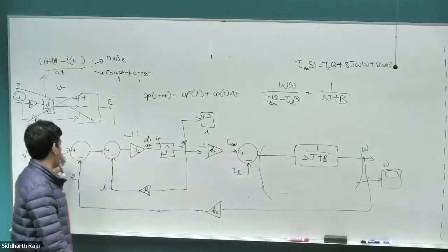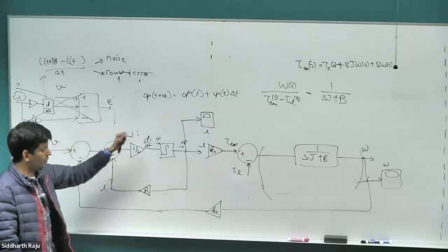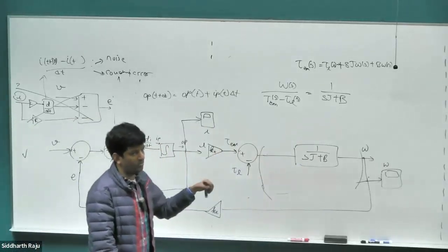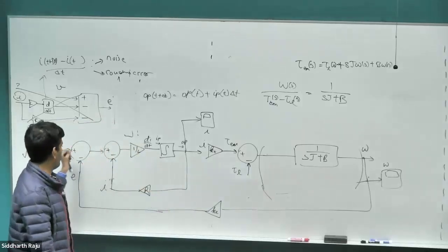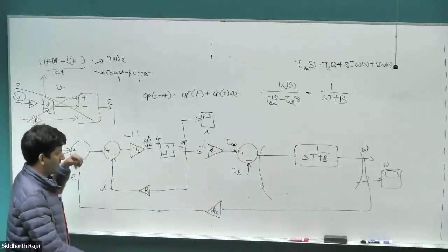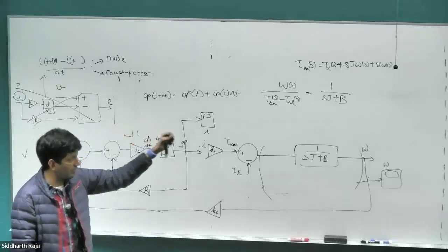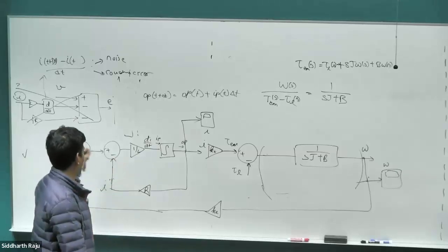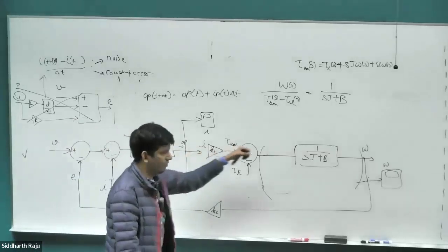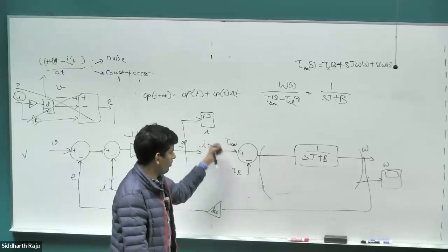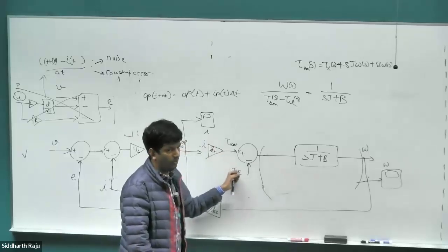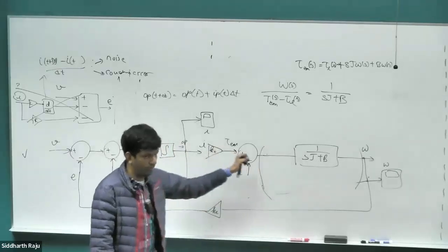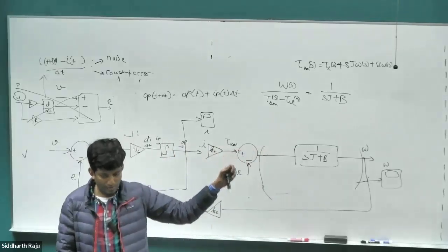In those cases, if you want to start from time equal to zero, wait for it to settle down, and then do these load changes and then analyze and then repeat this 1,000 times, it's going to take forever. So what you would rather do is apply some voltage, theoretically calculate what the steady state conditions are, which is what we just did a few minutes back, by making all the differential terms zero, and then initialize those integral values to the steady state value. And then you can go through quick iterations of just changing the step load for multiple different values and get the results really quickly, instead of having to wait the whole time for it to come to steady state and then start to apply the values.